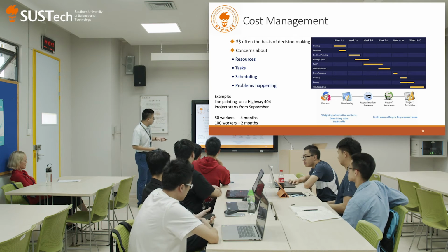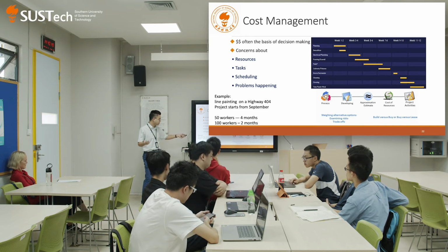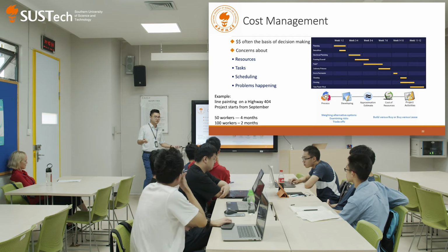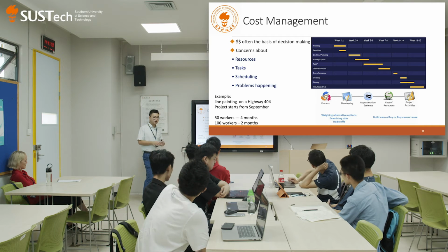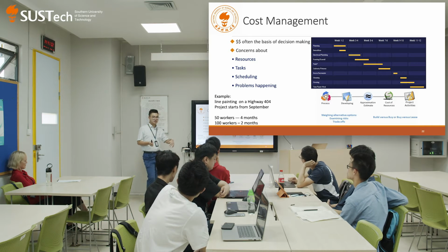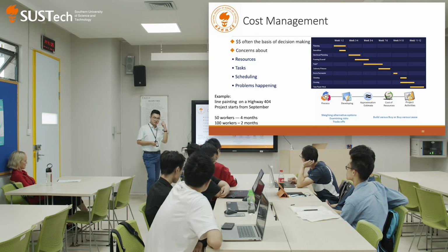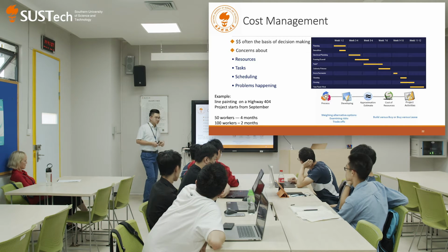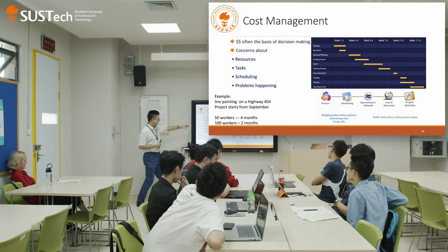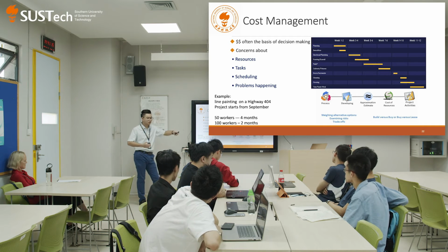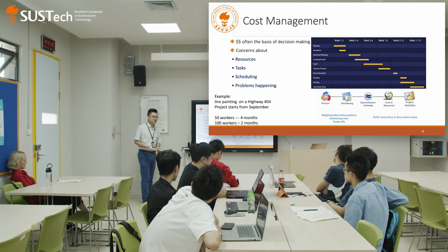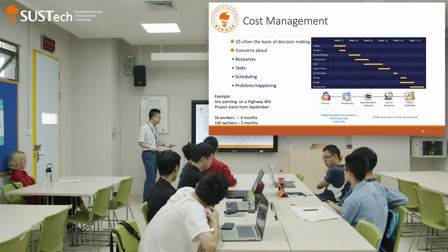And I also need to look at the weather, right? The climate, the weather. Because it's September, and after 2 months pass by, it will be November. Canada is already going into winter, it's very cold. So the labor, the working efficiency is slowing down. Right? We need to take this into consideration. The workers' efficiency in September and October will be quite different from when they work in November and December, in such a cold winter, right? Minus 20 Celsius, right? It slows down the working efficiency.